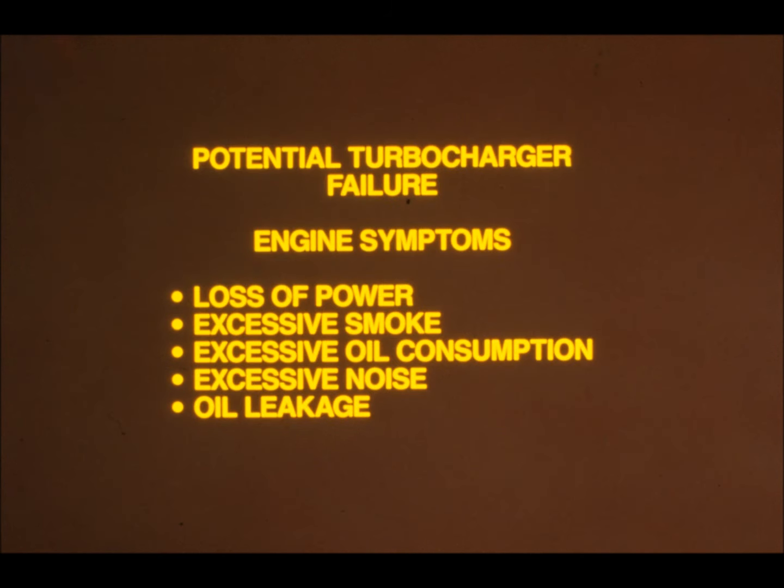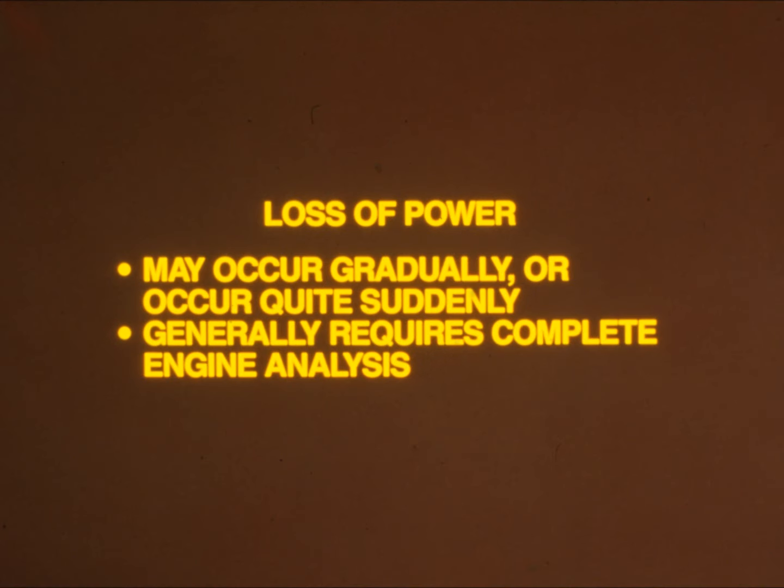There are 5 basic engine-related symptoms that indicate a potential turbocharger failure: loss of power, excessive smoke, excessive oil consumption, excessive noise, and oil leakage. A closer look at these symptoms will provide some additional direction for planning the analysis. There are many possible engine-related causes for a loss of power. It can occur gradually over a period of time, or may occur quite suddenly. Generally, diagnosis of loss of power complaints requires analysis of the complete engine.